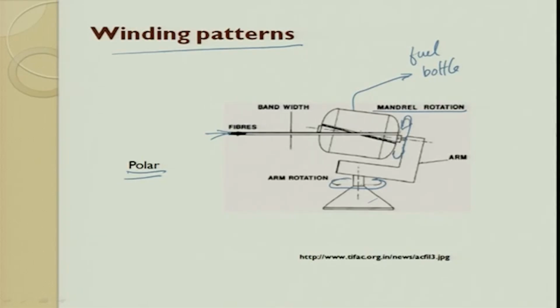Then what they do is, they always use a split mandrel, something like this, and in the center they might have a center core, which is tapered. So, they release this taper by hitting at one part, then the distance is reduced, and then they slowly remove it out. So, we always use collapsible mandrels. These mandrels are not an integral part of the product, they are only used to give shapes. For example, when I gave you the cement concrete example, it becomes an integral part, but generally if you want to make a pipe, we do not do it.